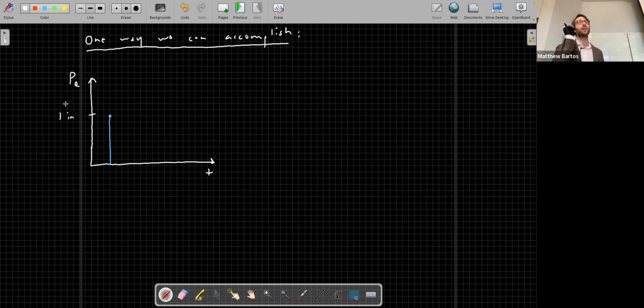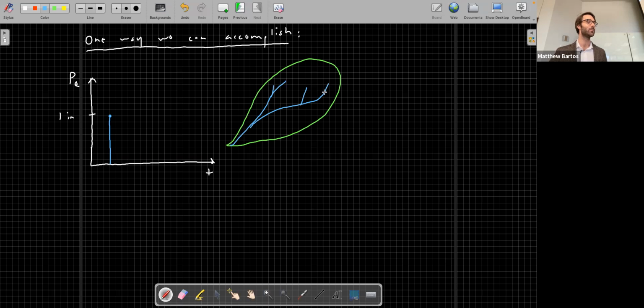We have rainfall that occurs at an instant in time, and we compute the resulting response of the watershed to that impulse. So we're dropping rainfall uniformly over the watershed all at once with a unit magnitude. And we can characterize the response to that unit impulse of rainfall at the outlet.